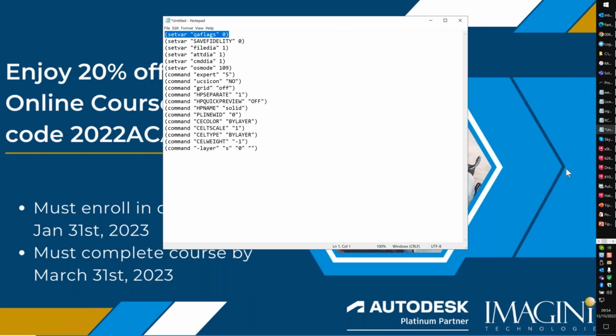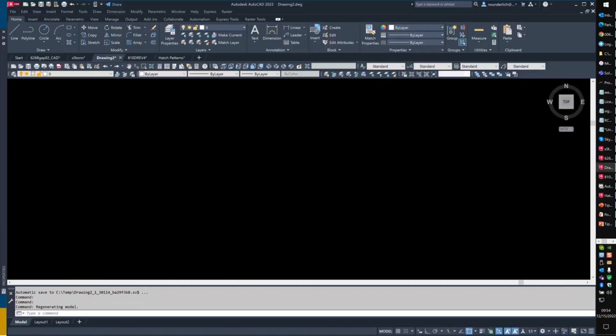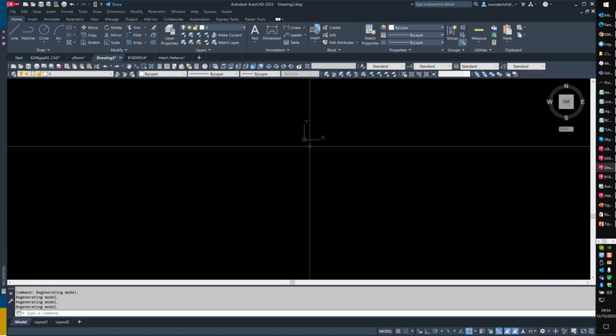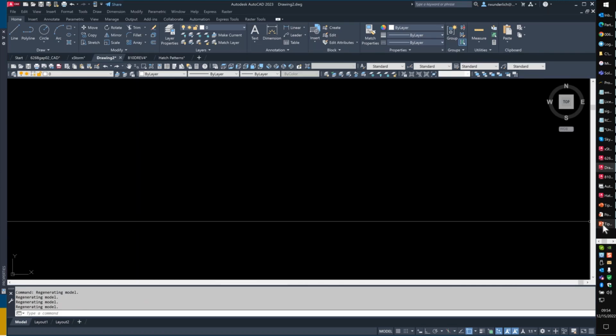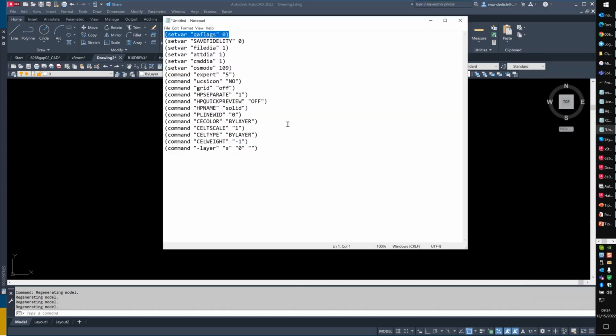Well, let's open up AutoCAD and we'll talk about these. So I do not like my UCS icon here set at 0, 0. I like mine to always be set to no origin, which is setting it here, so it always stays in the lower corner. And if I have a little square, I know it's on 0, 0.